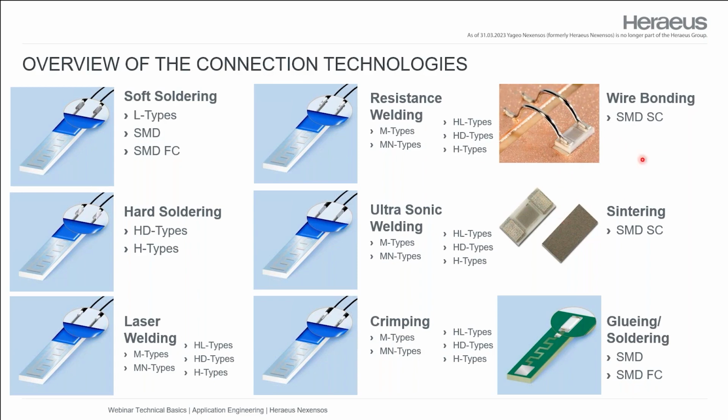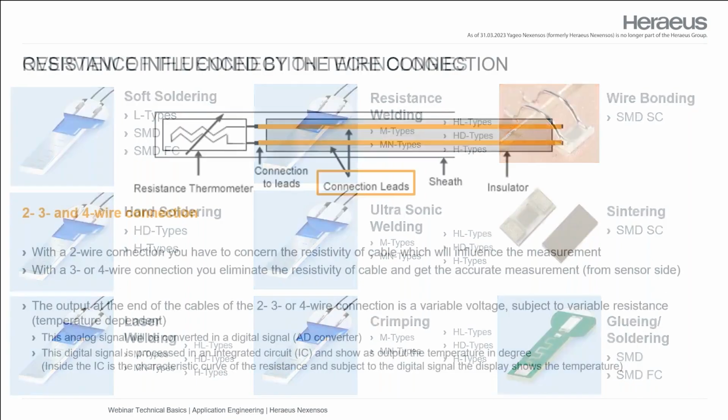This sinter technology is getting more and more popular because of the use of new materials in power electronics, for example. We come to that point maybe in the next training where we speak a bit deeper about applications. And then we have for sure some applications for PCBs. And then you can use solder technology, gluing technologies, and so on for the PCB. We have for this situation a flip chip version and a normal SMD version. We see the differences later.